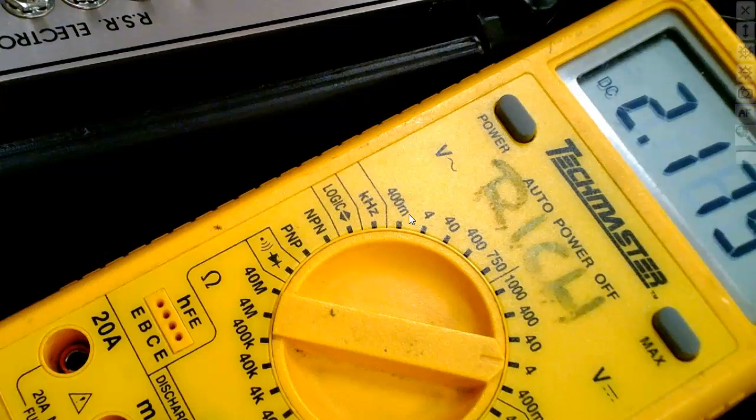Well, the diode is constantly switching between reverse and forward for every alternation. So it's forward bias. Anytime it gets above about 7/10 of a volt, it's going to let the negative alternation come through and block the positive.